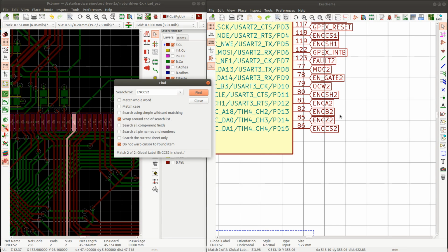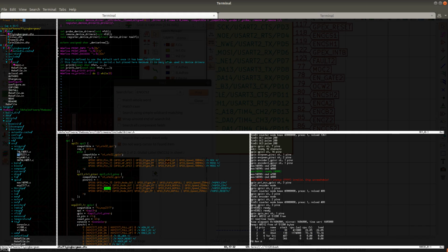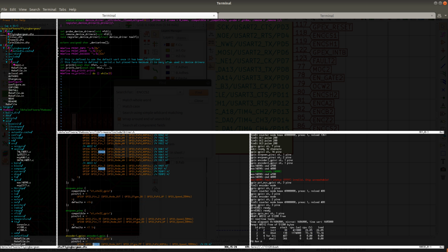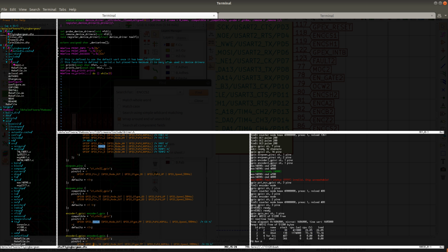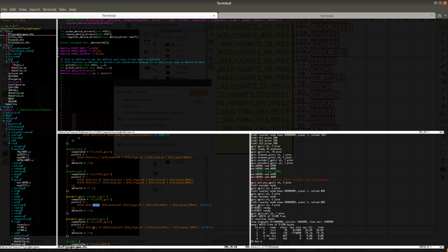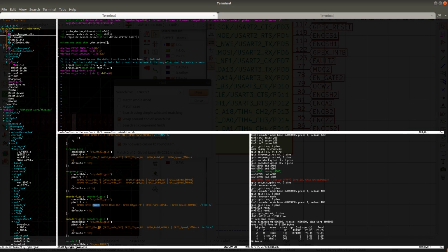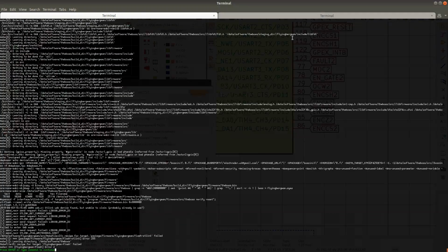I'm going to see where I have the NCS1 configured, PD4. So, pin 4. PD4. Got PD4 there, but then I don't have anything for the... Or actually, yes, I do have it. PD14. No, PD15. God damn it. Of course. So maybe I just didn't have the CS pin. That would explain why the driver cannot communicate with the chip.